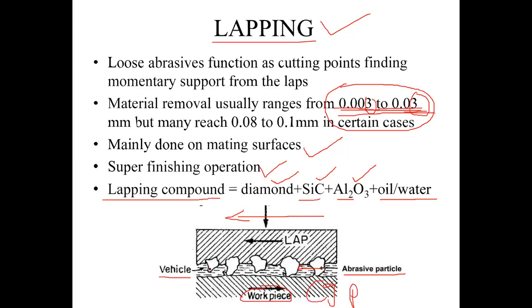On this you are pouring the slurry or abrasive particles, and this is not the tool. This is acting as the workpiece. The process is the same, only the things are quite opposite. Your workpiece is held and reciprocating, and whatever surface plate is there is stationary.